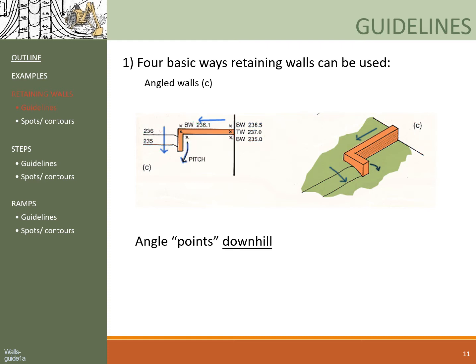For this type, drainage design should pay attention to two areas. The first area here, again, you need a small swale to direct water away from the wall. The second area is that the slope needs to pitch in a way to drain that corner, this corner, outward. Okay?